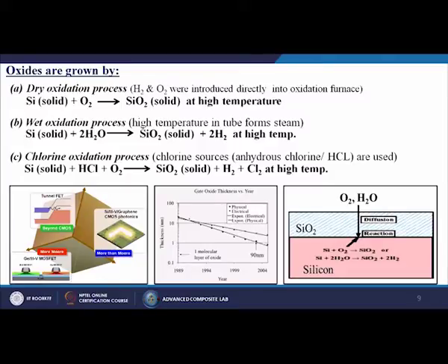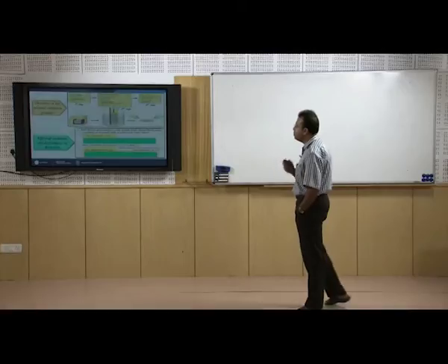And here this is the reaction which I was talking about. So, we have the silicon surface, then that silicon generates Si ions, and then we add some oxygen gas and water vapor, or maybe simple hydrogen gas, and they react with each other and form the silicon dioxide layer on top of the wafer or substrate.